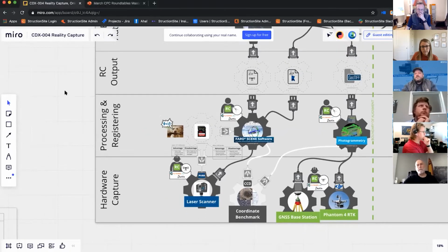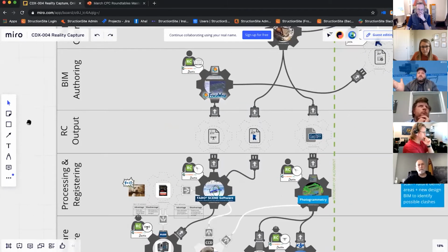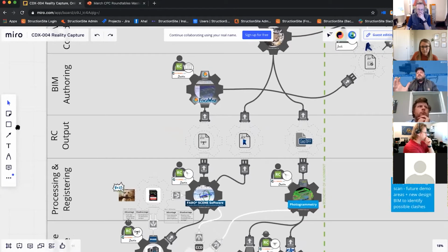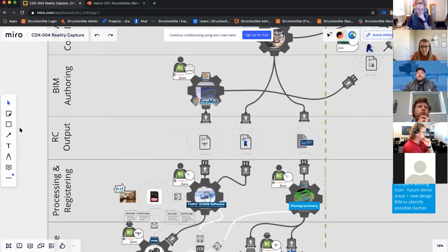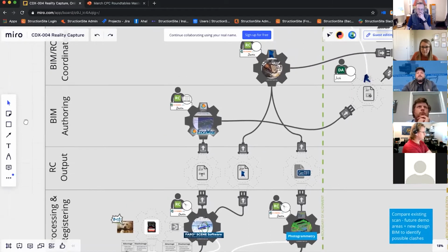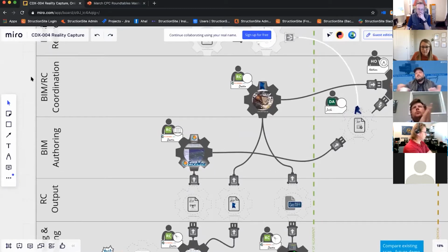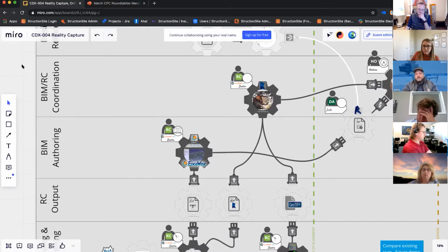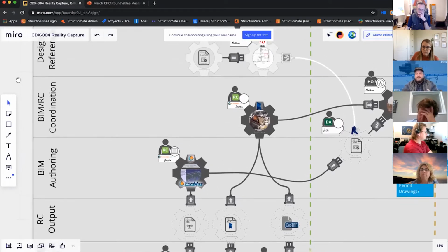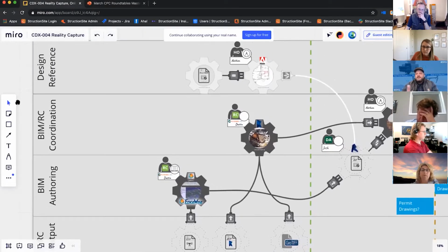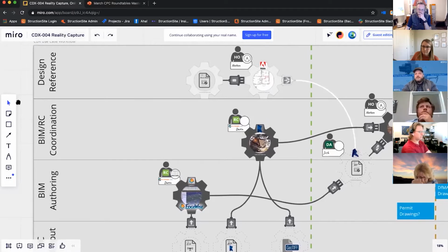In that same vein, once we do the photogrammetry flight, we'll process all that together in separate software, probably Pix4D. That's what we typically use at Flywheel. And we'll export those files to something that's really good interoperability-wise. We like to use E57 and LAS files from drone flights. Then typically we'll create a ReCap file just because the Autodesk engine prefers that, and it works really fast in the Autodesk products that we'll be using downstream from this.